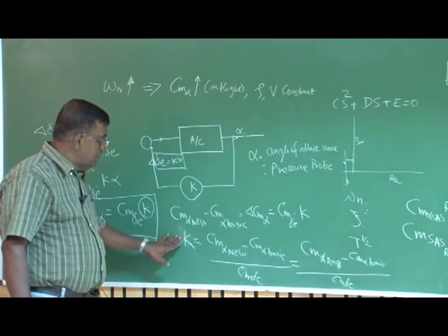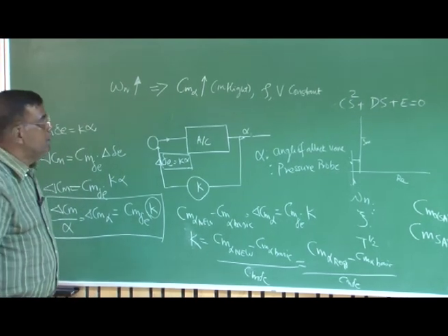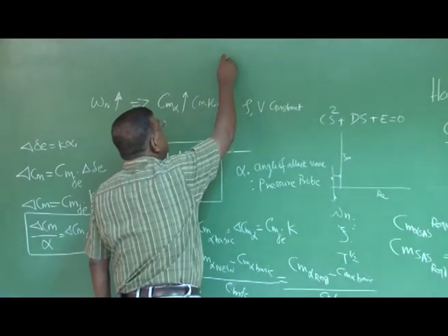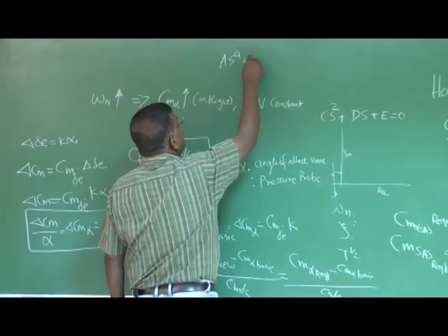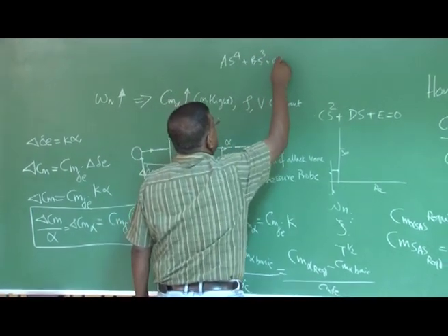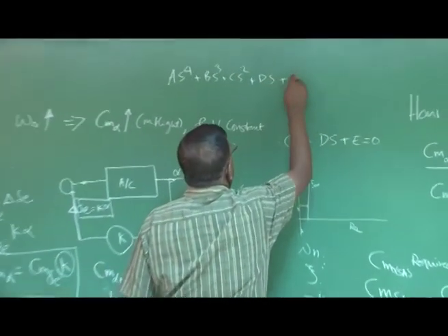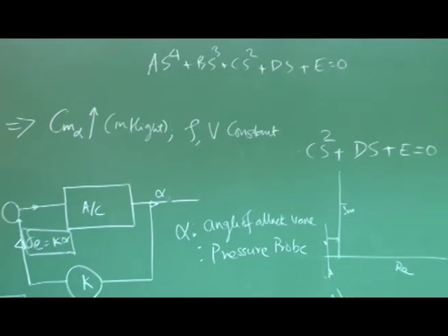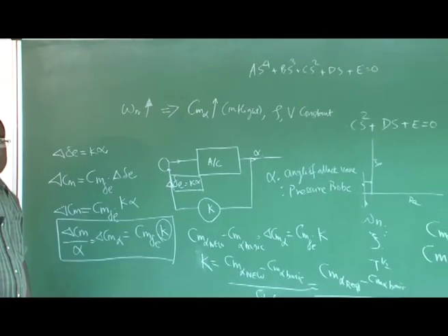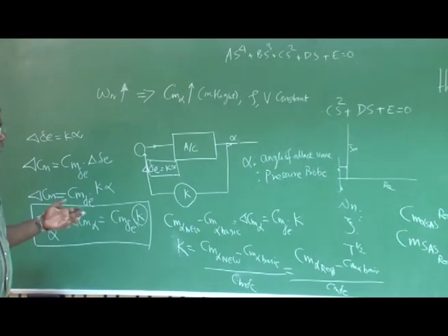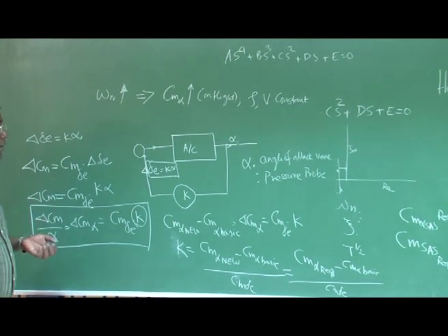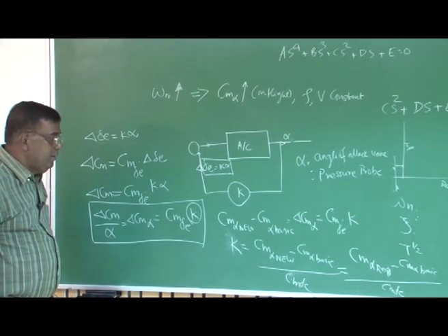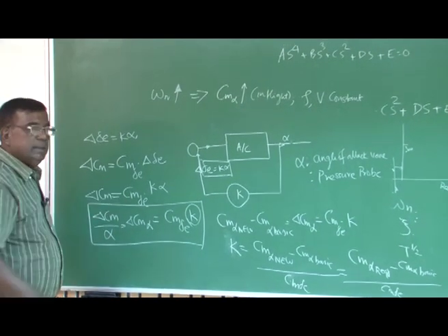But there are restrictions on K, because do not forget, finally whatever Cm alpha nu you are getting has to again go back to this. It has to be plugged into that equation to see whether the roots are what you are looking for or not, right? So that restricts. You cannot take too high a value of k, you cannot take too low a value of k. So those are engineering aspects, but fundamentally the approach is like this.